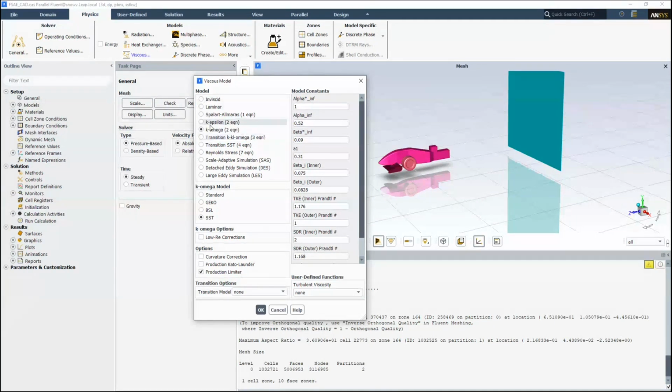The one we're going to set today is K omega SST, and that one's well defined. It's been developed over many years by a guy called Florian Menter, and they've done a lot of work in getting this model to represent reality at a higher level. It has an SST, the shear stress transport model, which can pick up what's happening in the boundary layer really accurately with minimal mesh elements. And this is a 2-equation model.